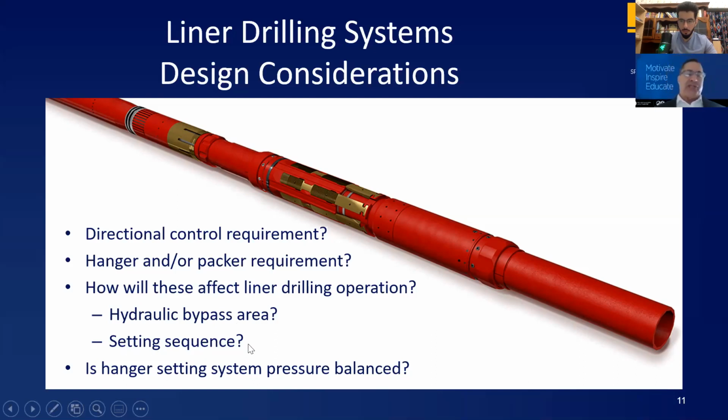The setting sequence. Now, I know on expandable liners, the cement is pumped prior to release of the liner setting tools, and in a conventional hydraulic system, it's just the opposite. The setting tools are released first. So that's a big consideration. A disadvantage of cementing prior to release of the tools is that you could potentially cement your running tools in place and have a fishing operation.